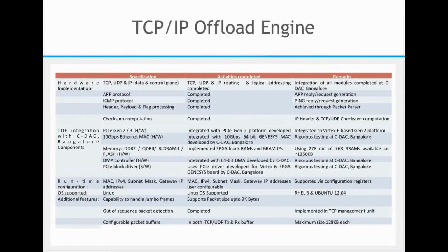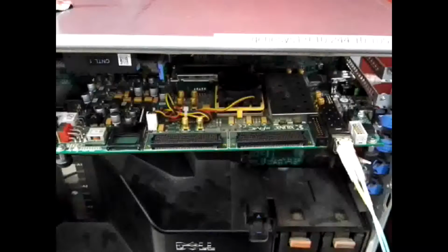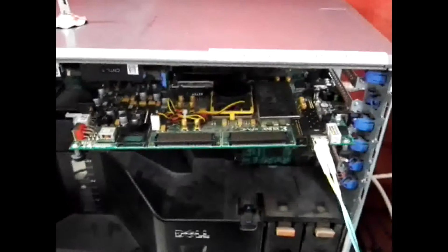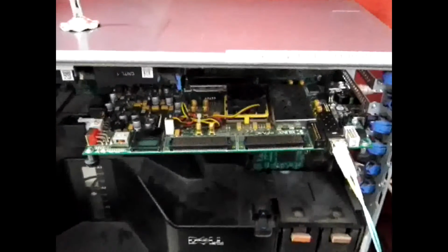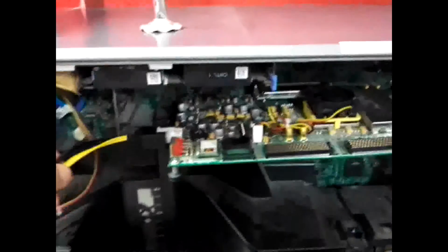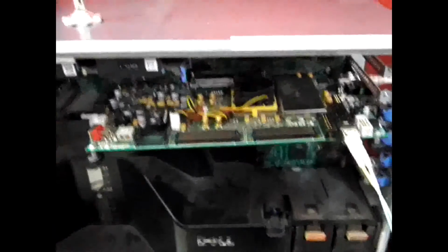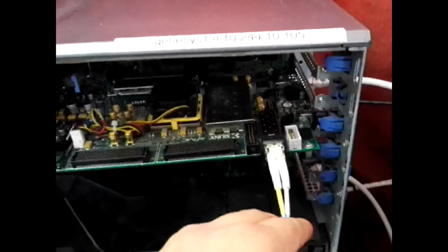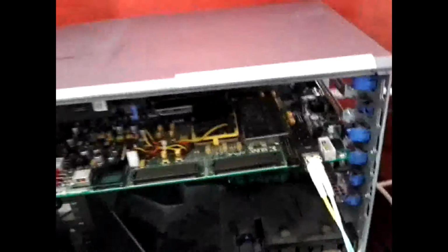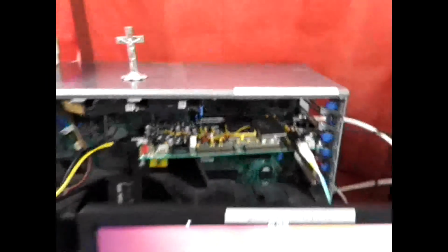The lab setup is described as follows. Following is the Virtex 7 evaluation board, which is connected by a PCI slot onto the server. It is powered by the ATX cable, which is powered by the server itself. A small form factor pluggable interface is provided to which the SFP cable is attached along with the standard RJ45 interface. The SFP cable is connected to the following client machine on the other SFP cage that is provided.